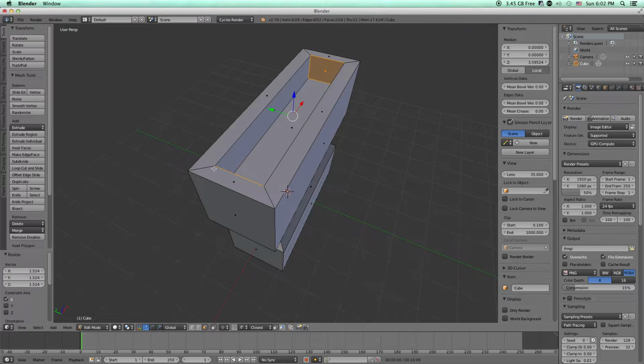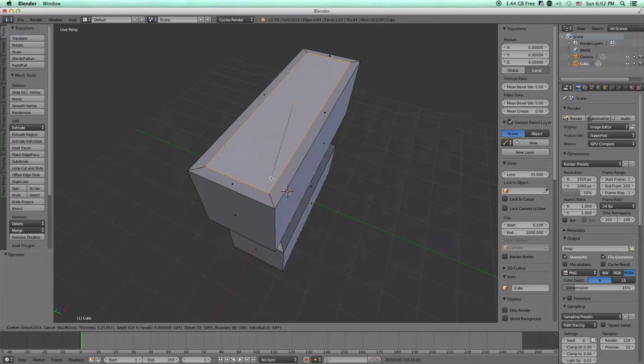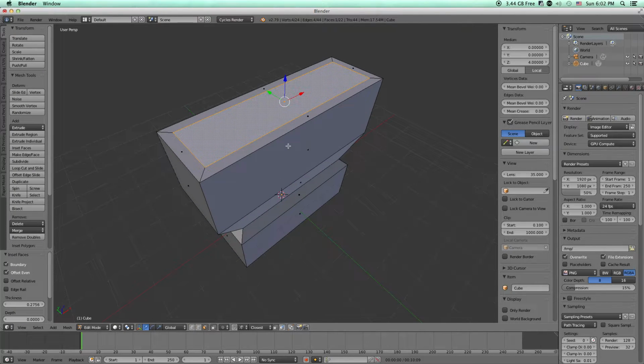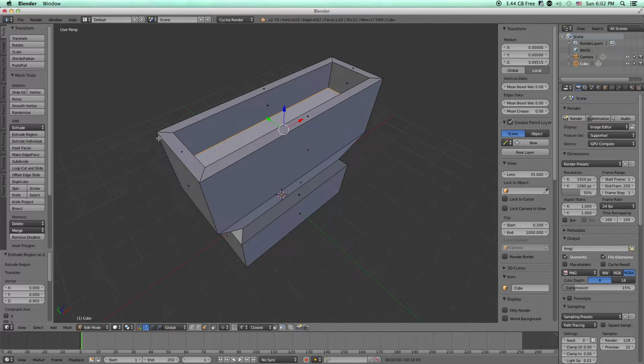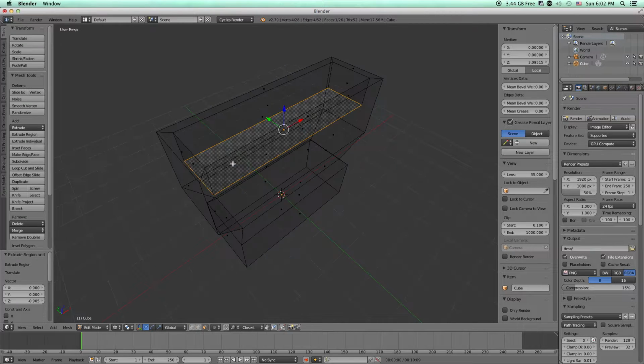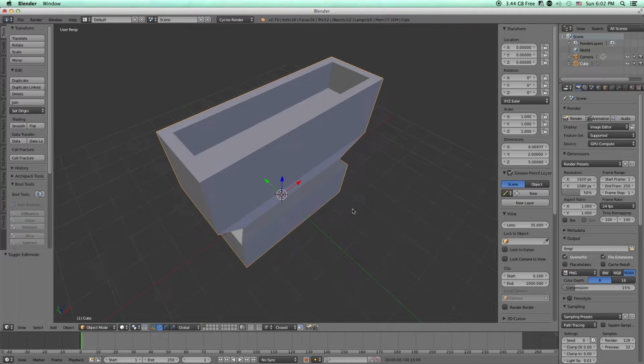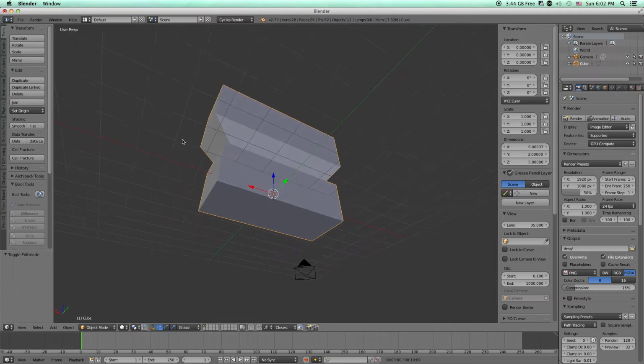And there's actually a way to better extrude something to where it always does this, but not to add too much, but I will show you. If you hit I, it will, I guess, more uniformly pull that in and kind of skips a step there. So if you extrude down, now you have this perfect cube. So if we go out of edit mode, we have our object right here.